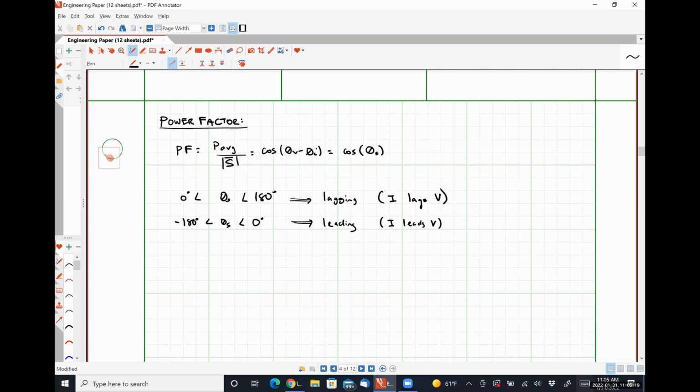We can fix this by using a process called power factor correction, which we're going to talk about a little bit later in the class. But effectively, as a home consumer, you're never going to have to really worry about that. Even if you have your dryer and every fan in your home running at the same time, because effectively your street is all connected together in one string, there's no way really that your individual power factor is ever going to dip below probably 98%.